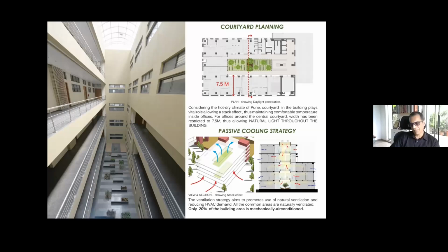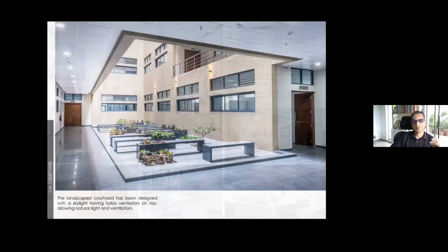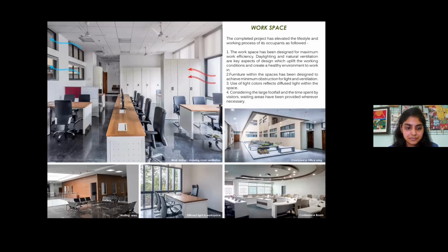Again, it gives you privacy, because especially these IT buildings, they visualize all glass buildings. They think without using glass buildings cannot look modern. But I'm sure that this kind of structures look quite modern, and this kind of courtyards really work very well in a public building or office building. Where you see there is a turbo ventilator on top, which creates stack effect.